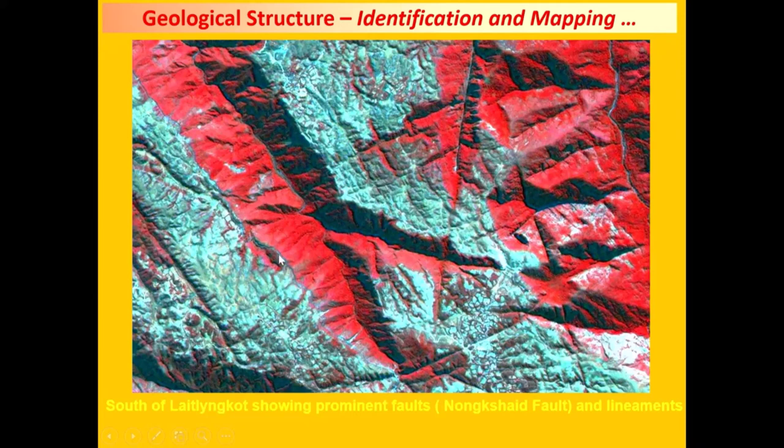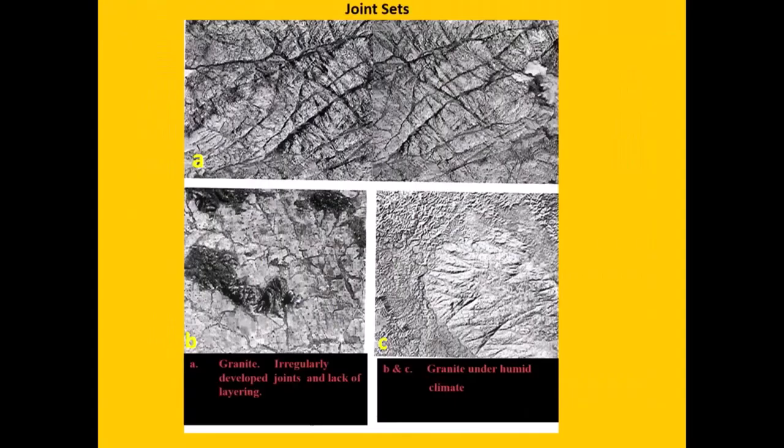By this you can get to know how strong the phenomenon has been, so that on the surface today we get only the lineaments. But if you are constructing a dam somewhere here, suppose, it's very close to these lineaments. Lineaments may act as zones of weakness anytime in terms of seismicity, and if you create a reservoir there, they can act as probable avenues for leakage or seepage of water. So that's how they are important.